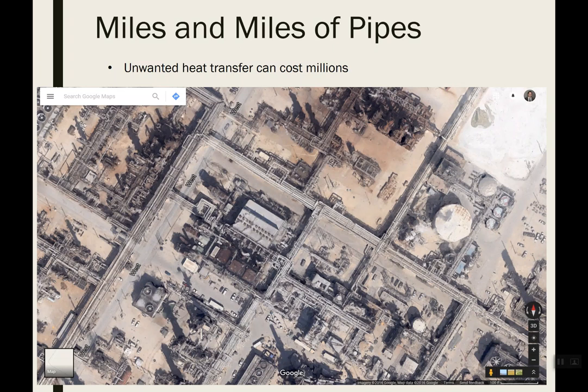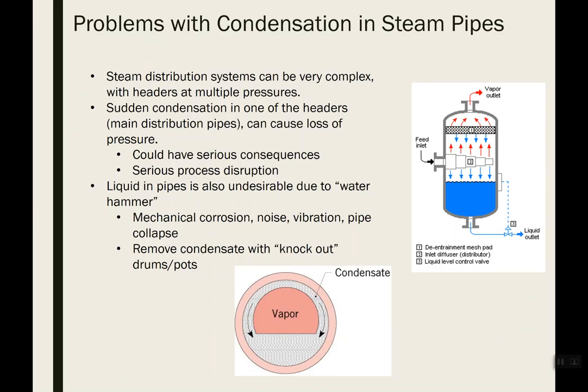So you get condensation happening on the pipes. If those pipes were near their saturation temperature and pressure and you suddenly remove heat, what's going to happen to that steam inside? It's going to start to condense, and fairly quickly. And the fact that condensation leads to higher rates of heat transfer was really a bad thing. In these big rainstorms, we would see our steam pressure go down really quickly, which had the potential to shut down particular units that I was responsible to maintain.